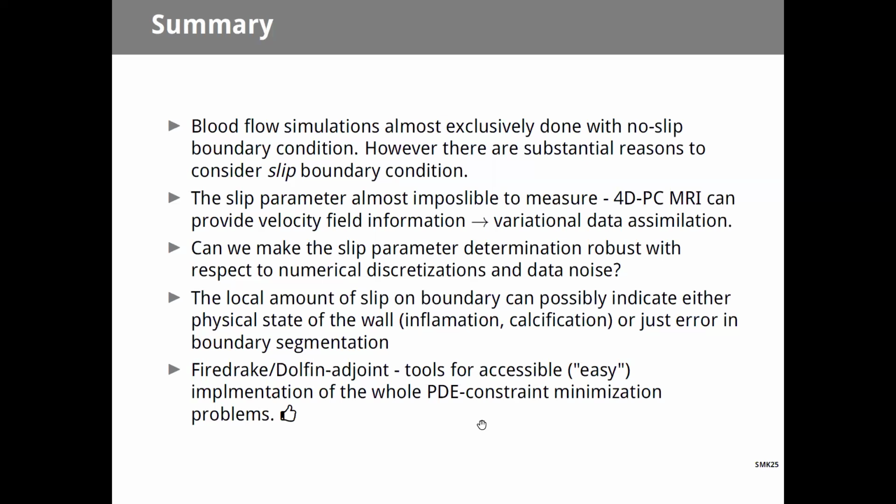There is a big difference in the computational time because of the direct solvers somewhere inside, so it scales with the number of degrees of freedom pretty badly. But what about the accuracy? Accuracy, of course, there is some drop of the accuracy if you go from Taylor Hood to the mini element or to this P1.